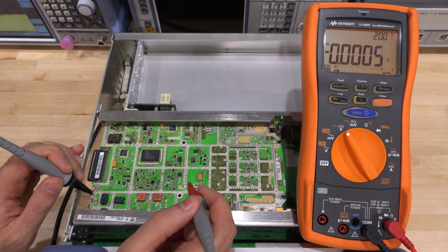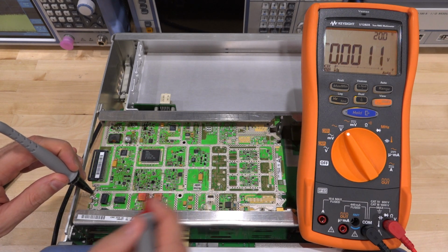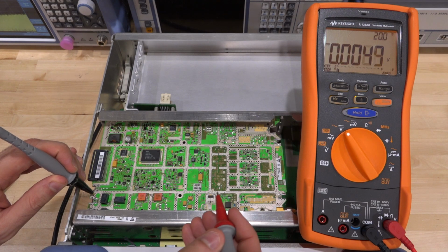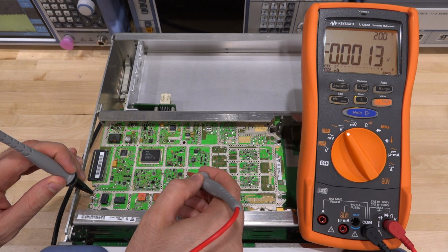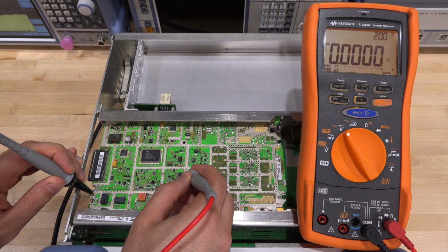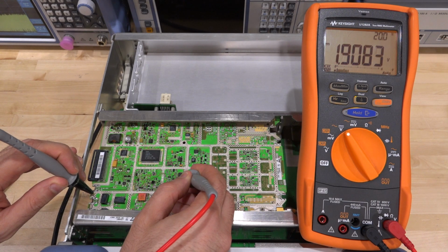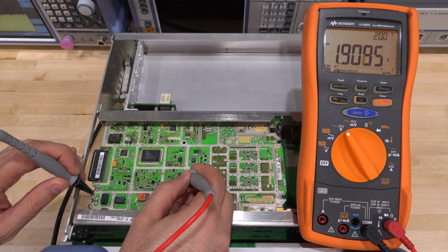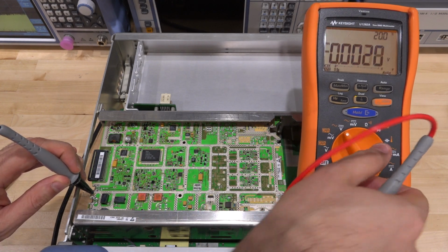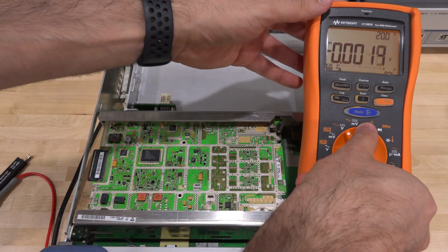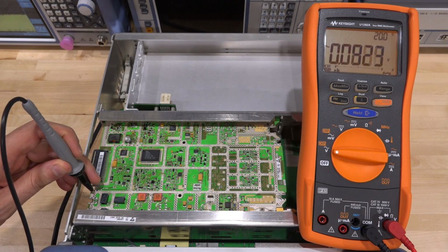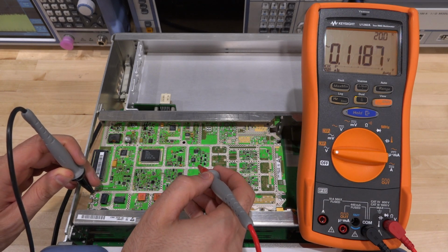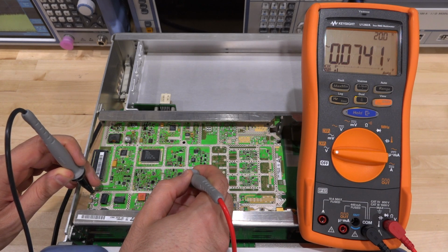Now, if I look at the tune voltage of the VCO, when the instrument is running and constantly trying to lock, we should see a jump all over the place if the rest of the PLL is at least doing something. Here's the tune voltage. There you go, look at that. It is definitely jumping all over the place. You can tell from the fast bar update at the bottom. We can in fact put this onto some AC voltage. I'm going to hold this, turn this into AC. We should see some AC activity. The frequency is going to be high. Some of the low frequencies might be cut.